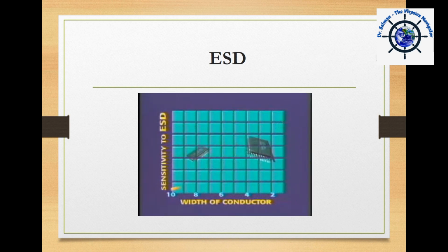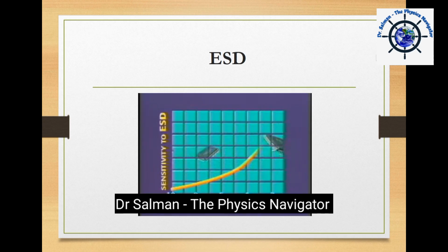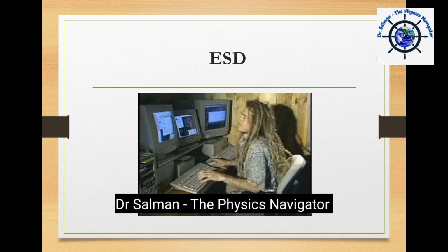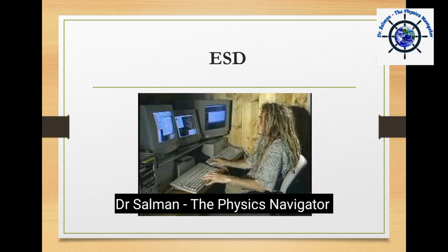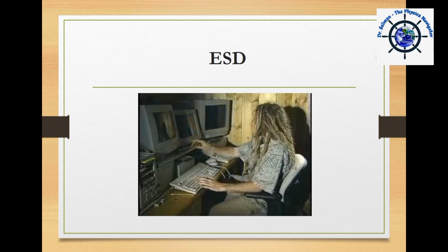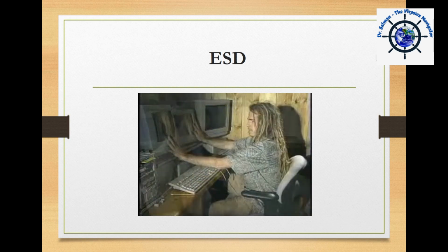The amount of voltage needed to damage or destroy varies from component to component. But as these devices become smaller and more complex, their sensitivity to ESD generally increases. Sometimes the damage caused by ESD doesn't mean the component will immediately fail. Instead, the assembly passes inspection, gets shipped to a customer, and then fails later on, creating a very unhappy customer.